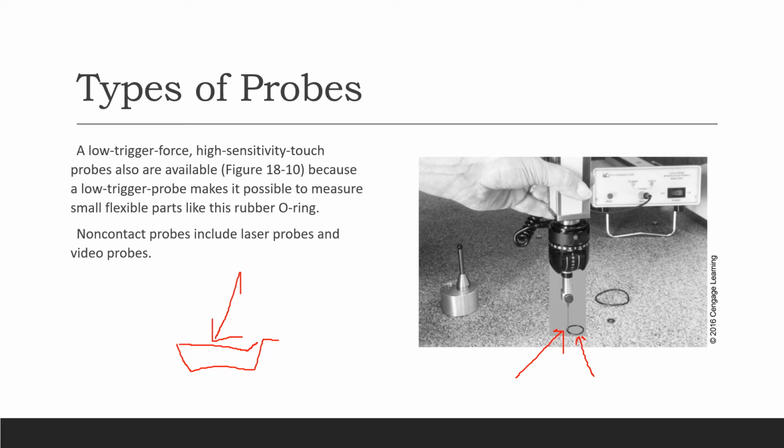Anyway, the real world is nothing but hard work, a lot of repetitions. And trying to measure this little one, how are you going to measure? You can measure with micrometer, you can measure with vernier, you can measure with height gauge, you can measure with gauges at all. So therefore, this type of part, how to measure, we have to measure by using probe and CMMs, okay?